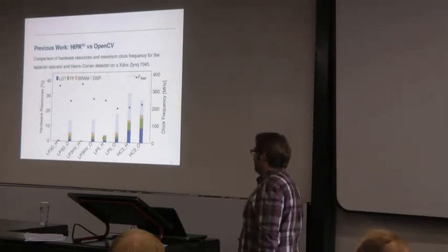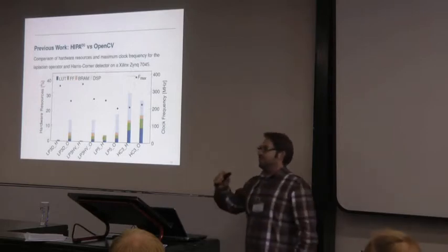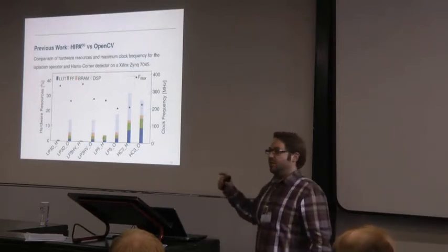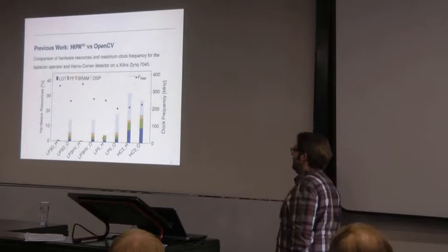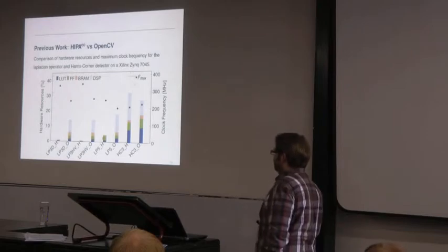On the other hand, usually you do a line buffer, which is the same height as your window. If you do some tricks, you can reduce this line buffer size, which is also why HiPAC uses some less BRAMs than, for example, the OpenCV implementations.